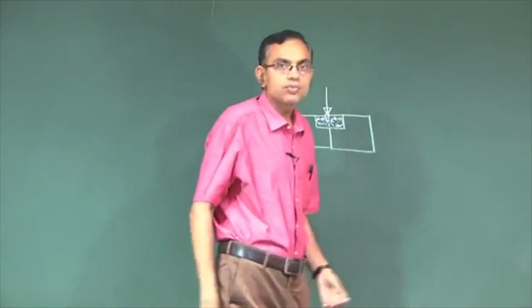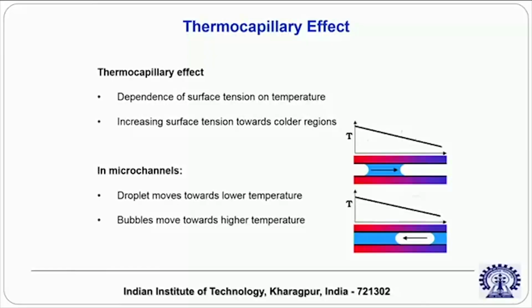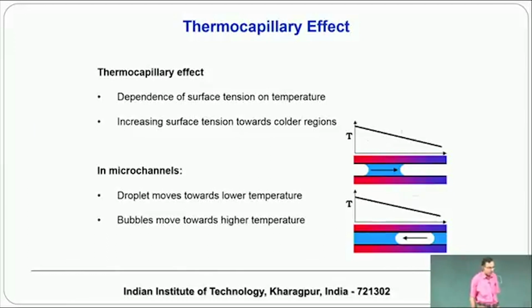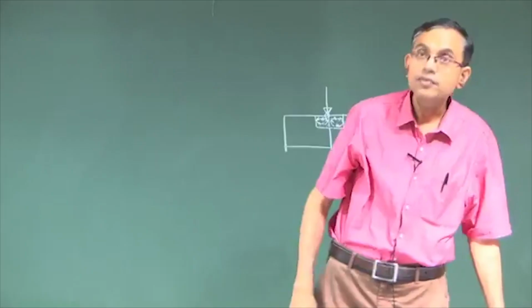Now, coming back to the slides, we will try to show some effects where the thermocapillary effect can be used to drive droplets and bubbles in microfluidic channels. Here, let me point it out, you will see that there is a droplet and this is a temperature gradient. It appears that you are paying for nothing to make the droplet move, but actually you are paying a cost by creating a temperature gradient on the surface.